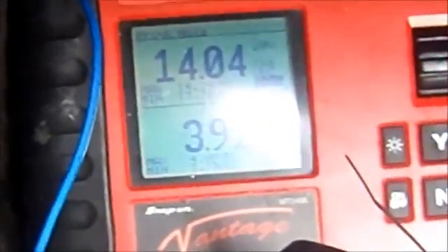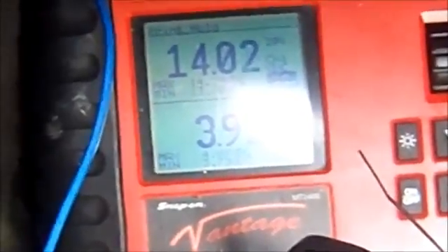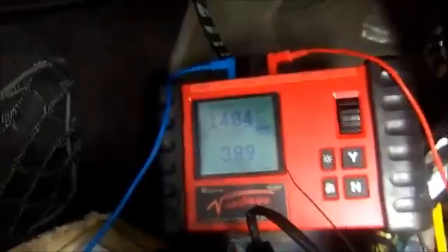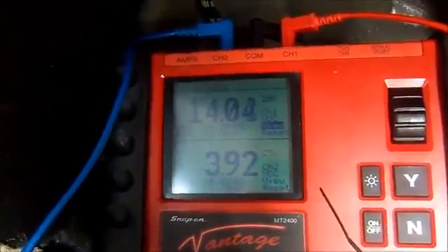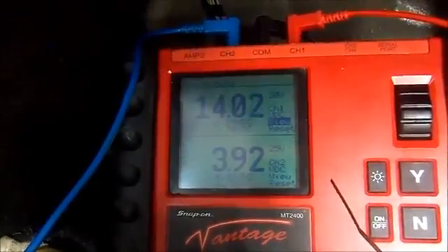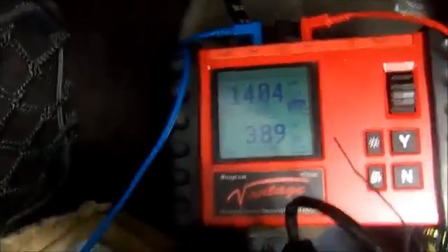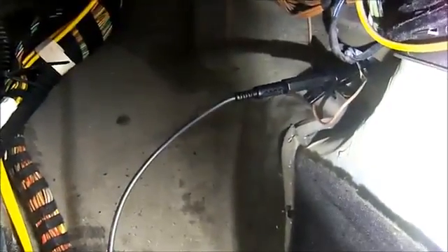And as you can see here, the transmission control module is not capable of producing the 12 volts that I need for my shift solenoids to operate. We got 3.92 volts, as you see here, and we do have good ground, and we do have good power. The vehicle is running right now. We have 14.04 volts, which is system voltage, and of course we have good ground, otherwise we wouldn't have that voltage. And here is the ground for the transmission control module, that brown wire.